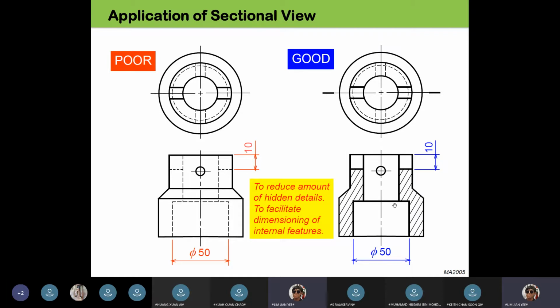If you cut a part in half, the shaded parts are the part you cut, while the non-shaded parts are like holes within that structure. For example, this part has a counterbore in the middle of the structure, as you can see in the second image. You wouldn't be able to tell this shape if you were only given the first view, so it helps a lot for general design.